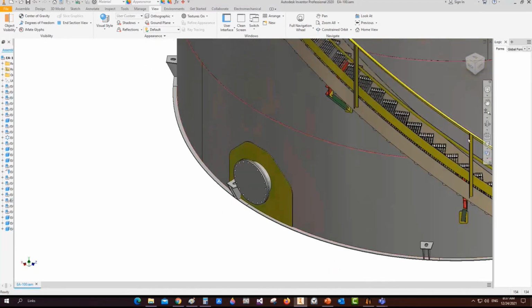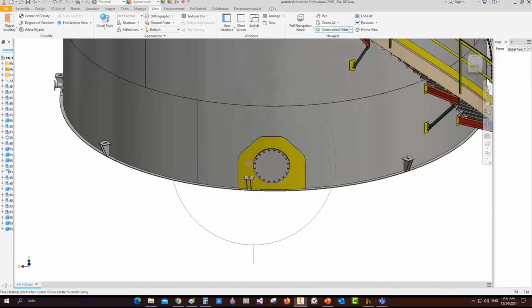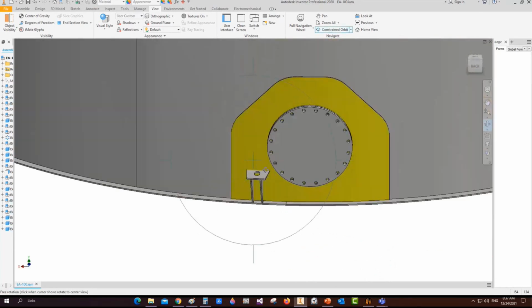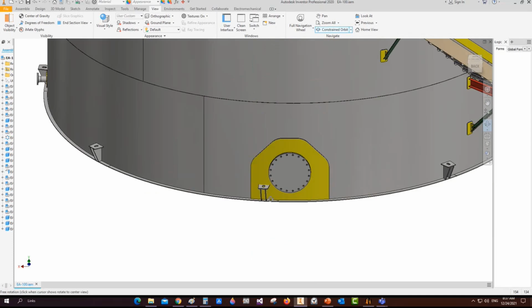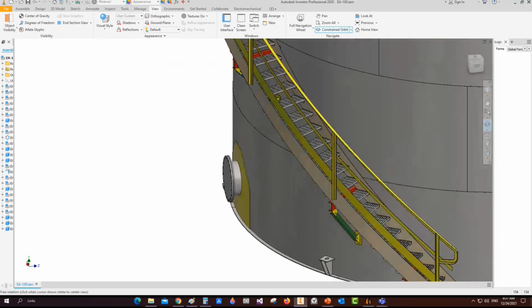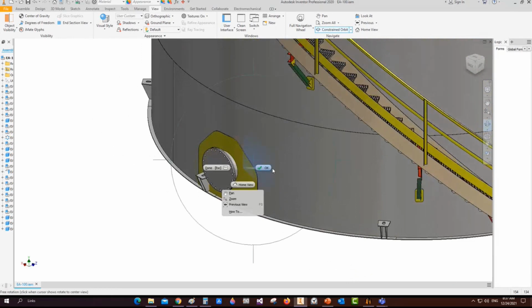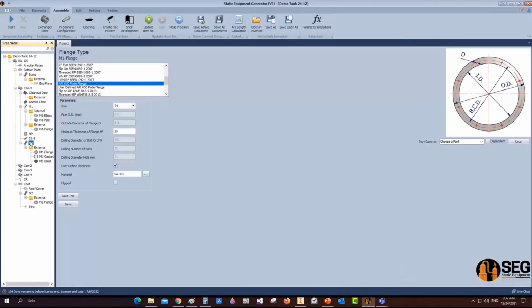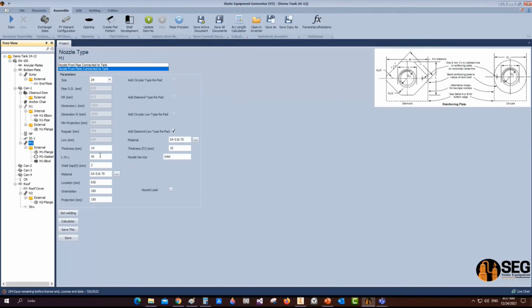Here we have this clean outboard. Now, we can figure that we have a clash or interference with the anchorage here, so we can rotate this Manway a little bit. So if we come back to the Manway here, let's change the orientation of this one like this, and increase the projection a little bit.